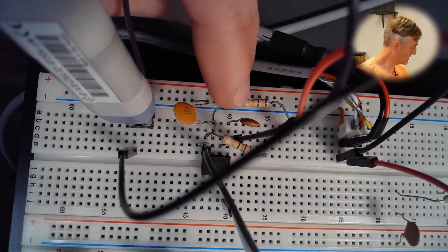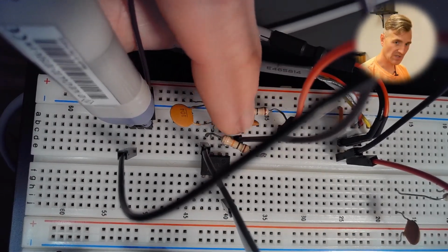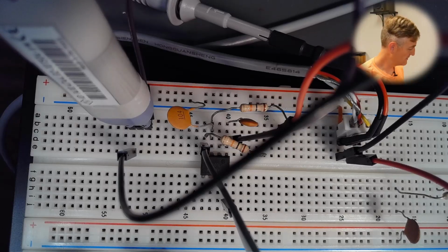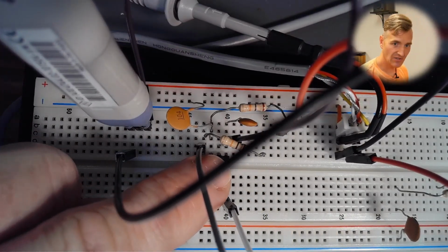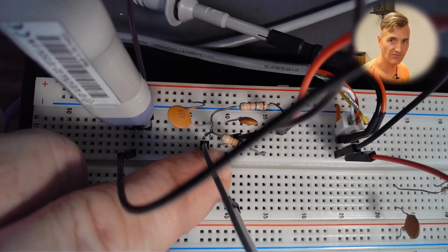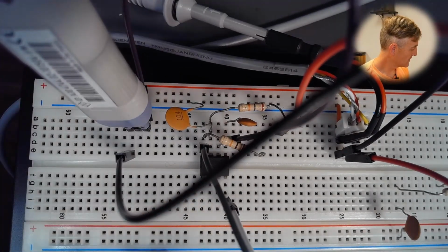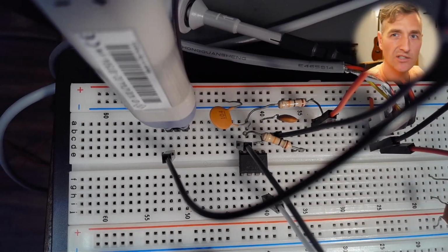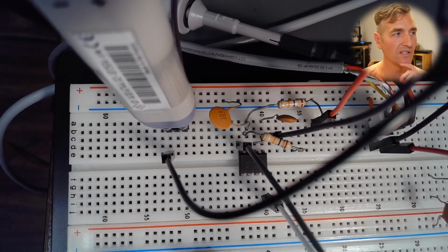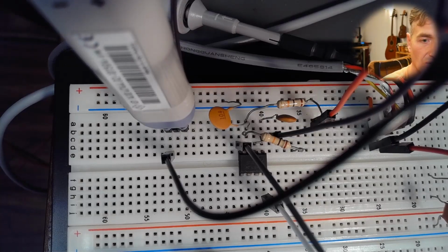I have my input resistor going to pin 3 and that mess of wires down there. And then I have a tiny little jumper from V out to V in negative. So I think I have it as non-inverting, although the frequency response, inverting or non-inverting, shouldn't really change, I don't think.